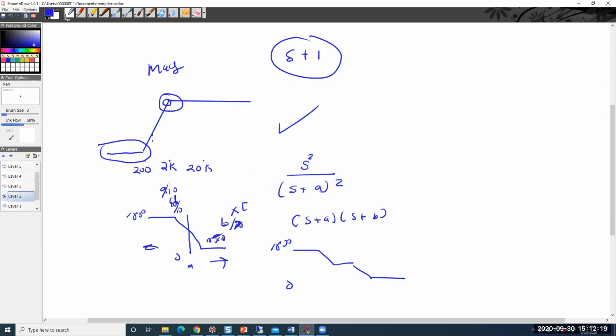So those were the 3 kinds of plots. And again, the phase would have been the same, except instead of 180 to 0, it'd be 0 to 180 for the high pass, where you would have like A squared, and whatever gain. Now the magnitudes, for the high pass, you could have a sharp slope, then the slope evens off and does that.